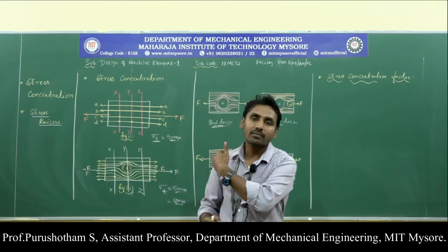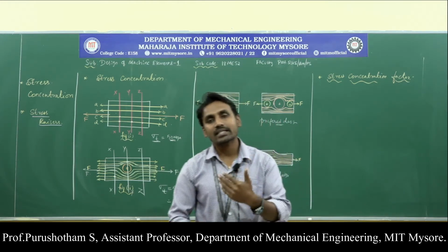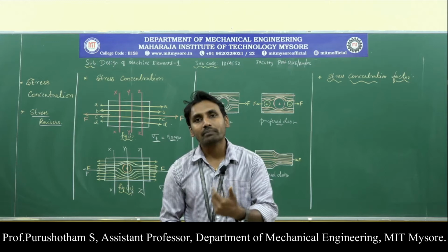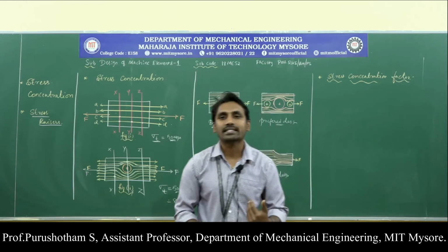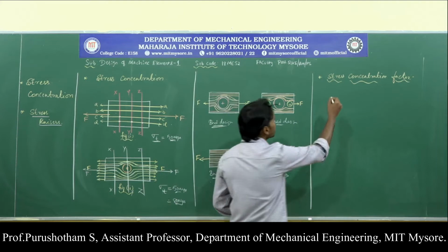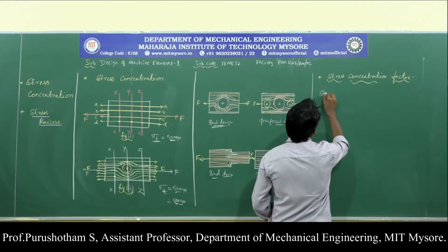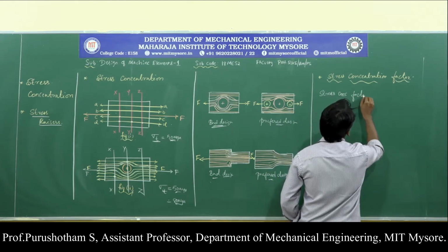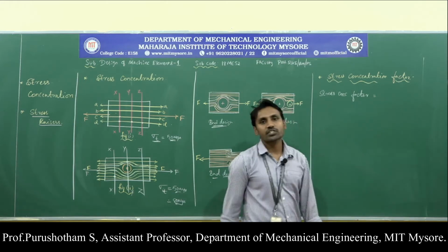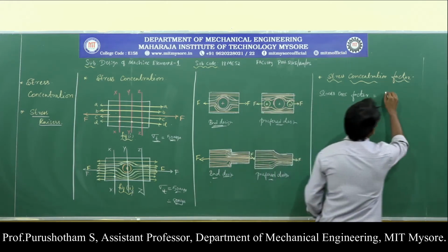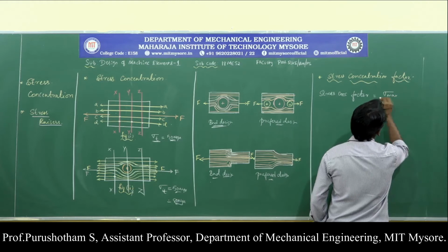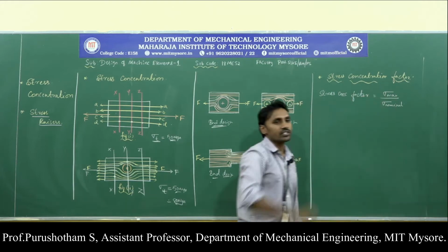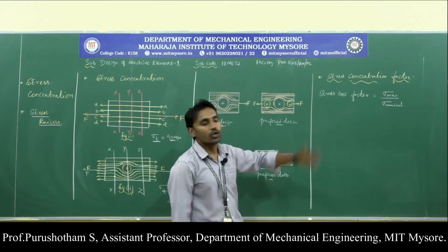So in Design of Machine Elements 1, we are going to calculate the theoretical stress concentration factor by using the theory of elasticity concept, that is, mathematical analysis of the theory of elasticity. The general expression for the stress concentration factor is maximum stress by nominal stress.